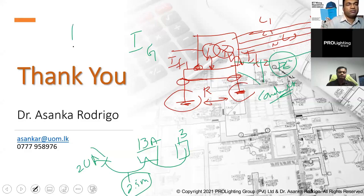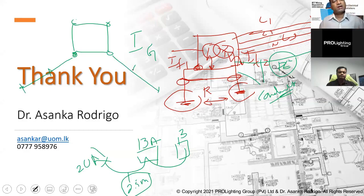Now, for example, let's say you have a building, I'm drawing the top view, with down conductors at different locations. In order to measure the earth electrode resistance and check whether it is below 10 ohms, you can have certain inspection points to measure. You can use a 3-point earth electrode resistance meter and measure in different directions, to see what your earth electrode resistance value is. But in terms of the safety requirement, you are not caring about earth electrode resistance for a TN system, because you have a low impedance path. So you don't have to worry about that.